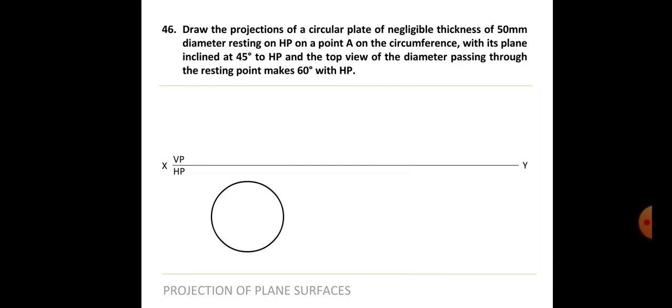Next, the circle has to be divided into 8 equal parts. So now there is no divisions on the circle. We have to divide the circle into at least 8 equal parts so that we get proper views in the next set of views. Okay, so you can see we have divided the circle into 8 equal parts.